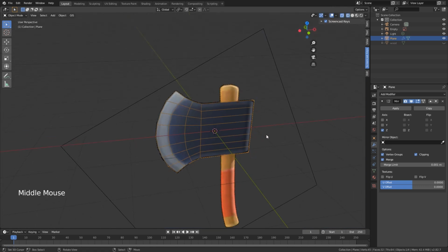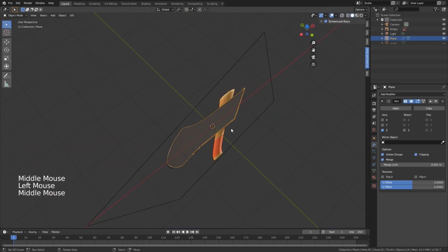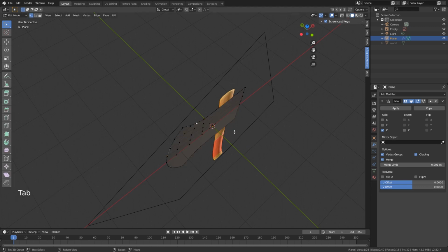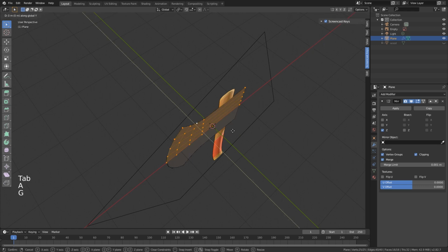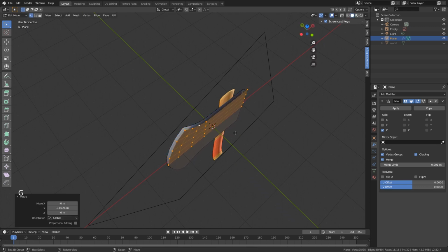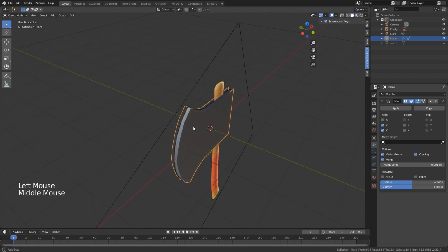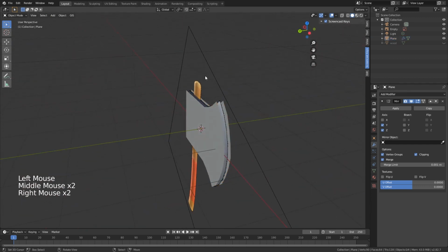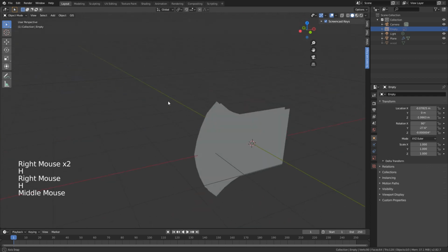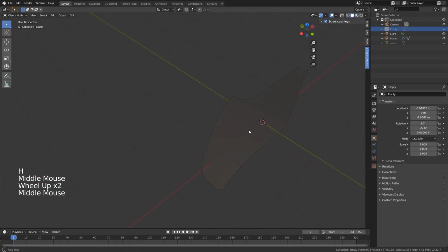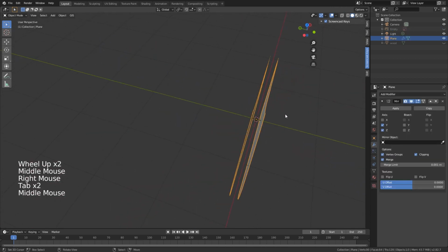So our side view is done, but we want some thickness in here. We can literally do this with the mirror modifier, but we of course need to go into edit mode and move this a little bit to the right. So around the y-axis, I'm just moving it a bit. Now turn on the y-axis and we can see that we have some thickness, right? They are just not merged together, but we have a certain amount of thickness.